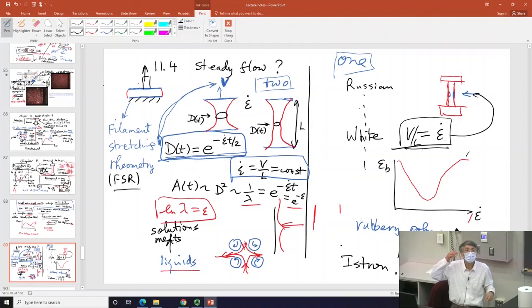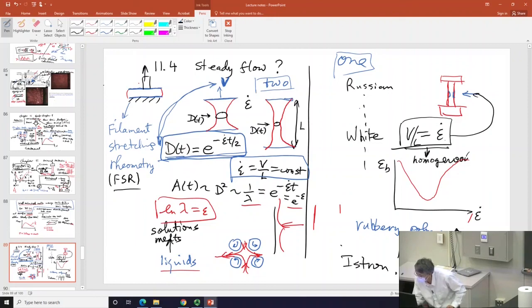In other words, what you are dictating is just the boundary, if you like, right? Because you can only hope that your sample behaves properly. Everywhere will stretch the same amount. But just like in shear banding, it doesn't. It breaks. This requires you to hope that your deformation is homogeneous, right?